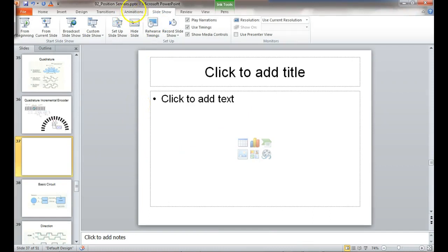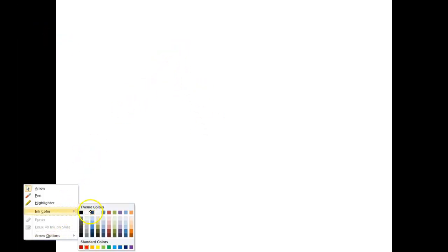What I would do in my program, if I wanted to run it to an exact angle, is take the total number of counts. What's our total number of counts per revolution? 2100, and I would divide that by 360. That would give me my counts per degree. And now if I wanted to run it 90 degrees, y'all understand? Yes or no? Okay. So what would our counts per degree be?